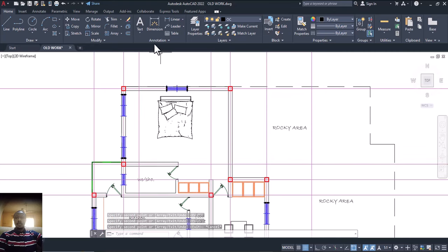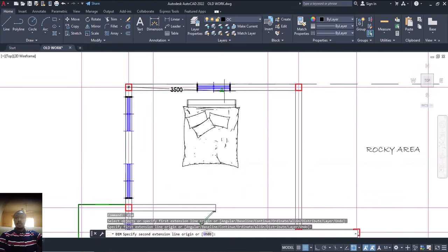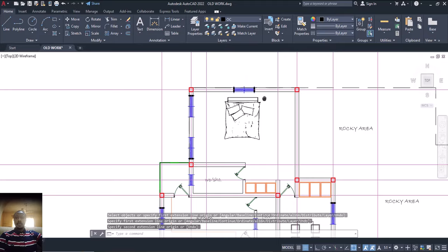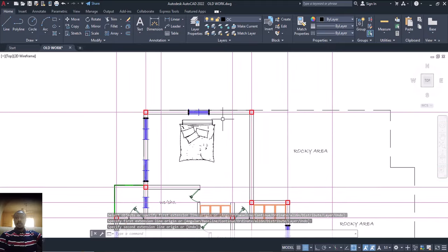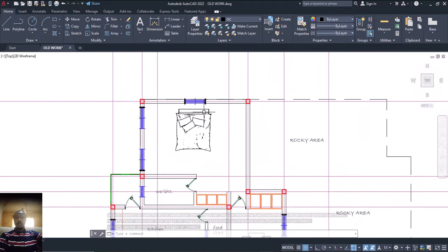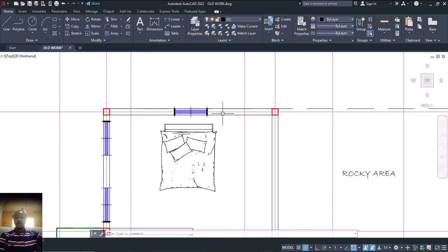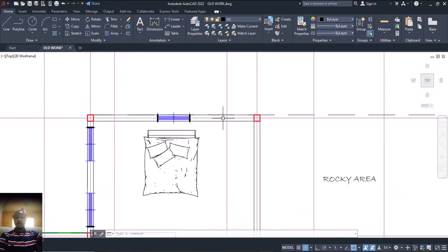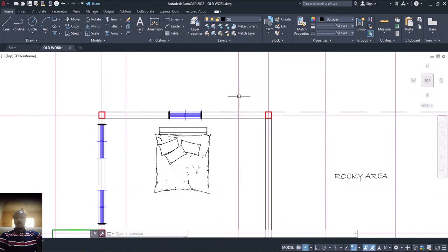Looking at this from here to here, this is about 6.2. As it is now, I can decide to leave it. But my beam depth might be increased a little bit, or the kind of reinforcement, since it's more than 6 meters. Even though it is by 225, let me just break it. Let me pick one from here. Let me see the distance first.